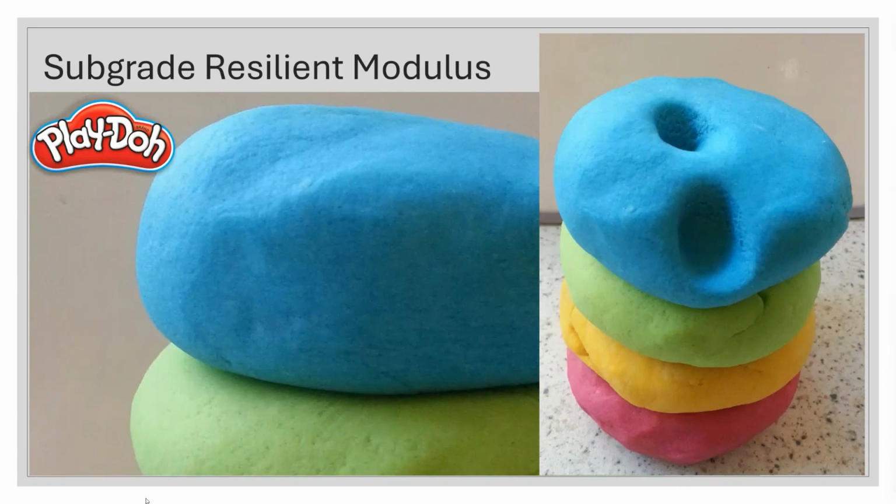So think of our pavement layers as kind of having that same reaction, a very quick moving load, like a Mack truck on the interstate. We're not going to see some of the same distresses on the interstate that we see, say, in a small city street at a stoplight, where a very heavy load sits there and it's going to be a very slow processing load.